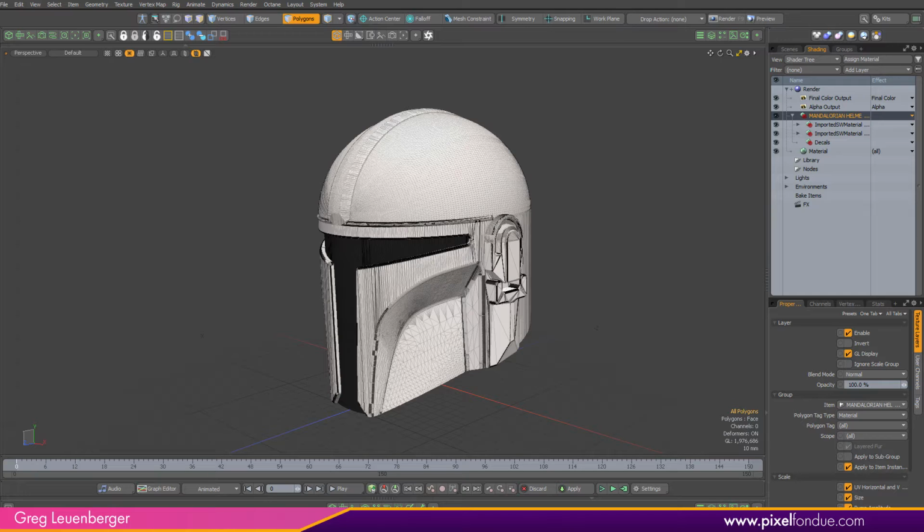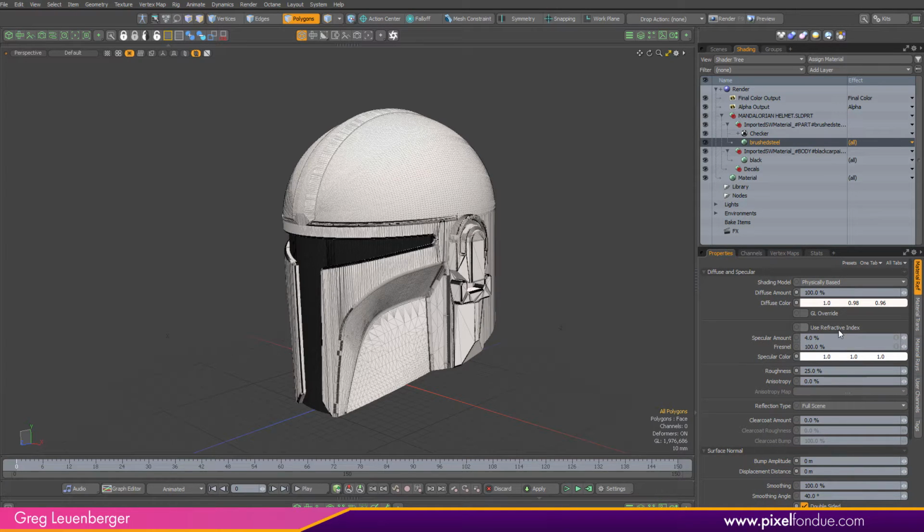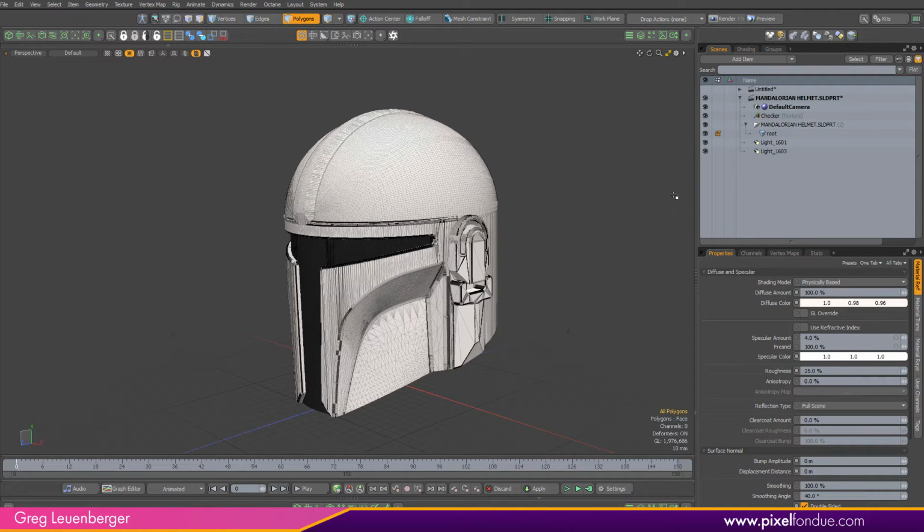Again, this is the collaboration between Luxology and Dassault Systems, where the MODO renderer was incorporated into SolidWorks, and so it actually has a MODO material library. And if you dig into these, you'll notice these names, it actually brings the names over. So there's brushed steel, and sometimes you may get lucky and it actually brings material properties over, but not always. And here you've got black right here. So the names are there, and it's actually useful when you want to go in and start texturing these things, doing your material work, because you'll see that these human readable names come over often with SolidWorks files, and that's a nice little bonus when working with SolidWorks files.